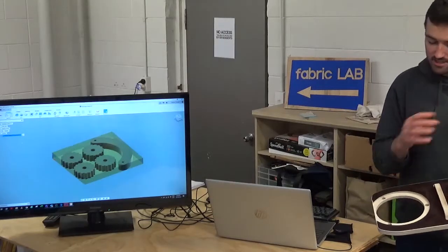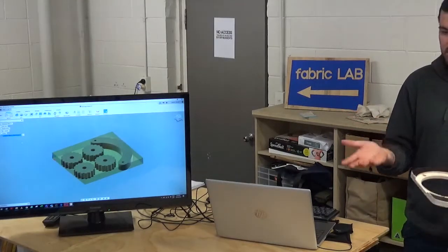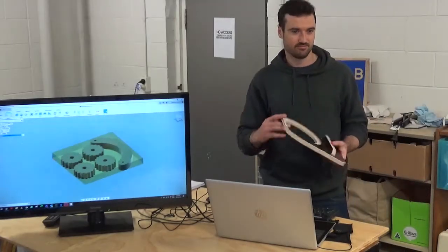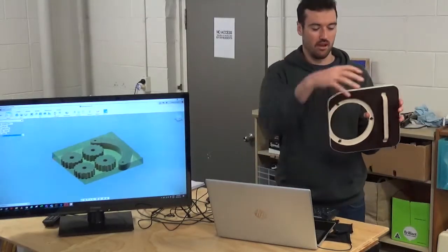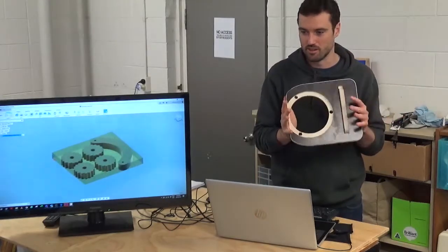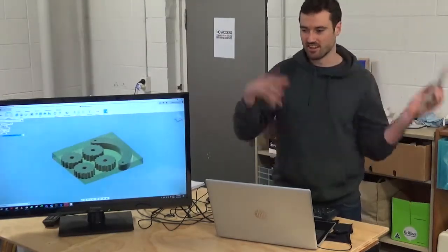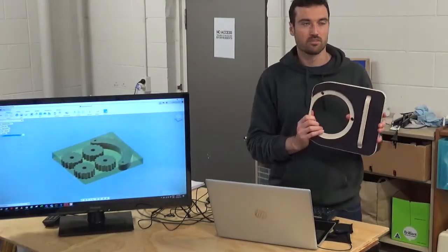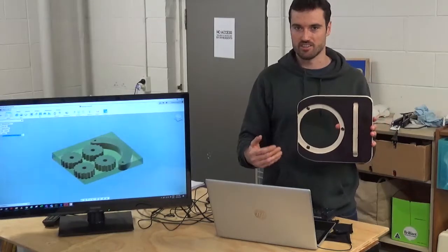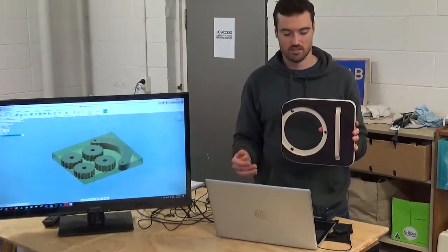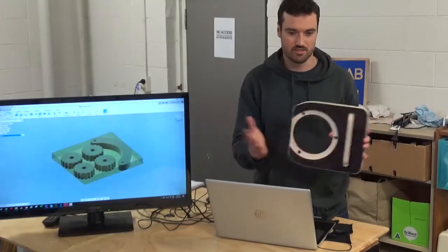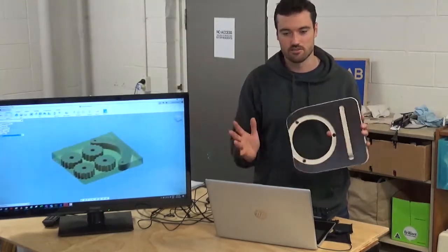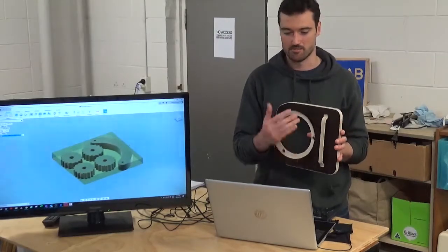And what's the reason for that? Basically, as you start cutting stuff out, you're weakening the piece of timber. The piece of timber is held in place with screws or whatever, and as you start removing stuff, it starts to want to move around. So you want to do the least intrusive operation down to the most intrusive. The first thing you do is the drill holes because it doesn't disturb things too much. The pockets don't disturb things too much, but profiling does, so that comes last, typically.